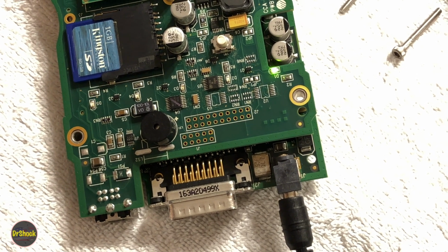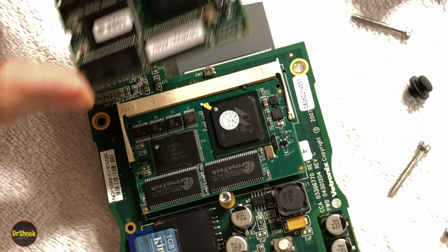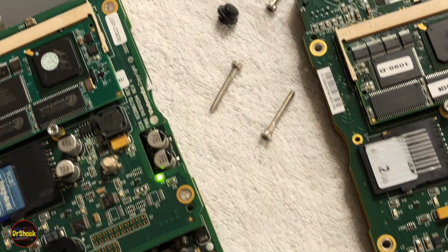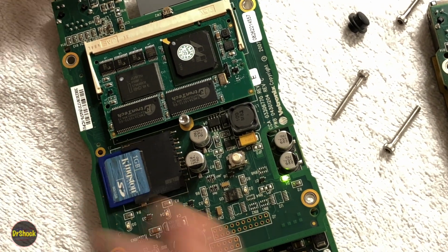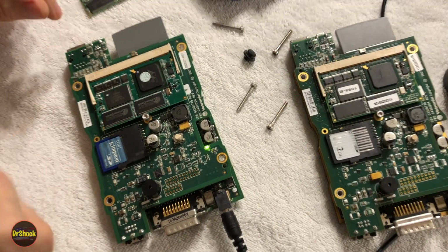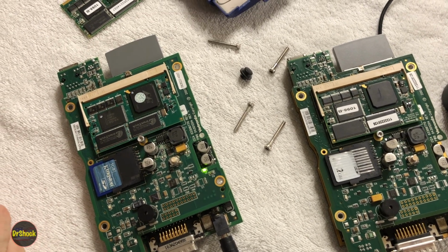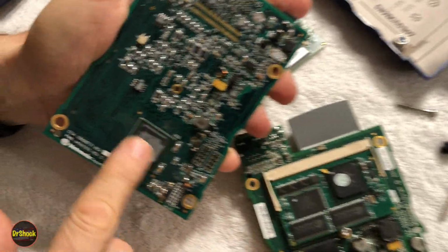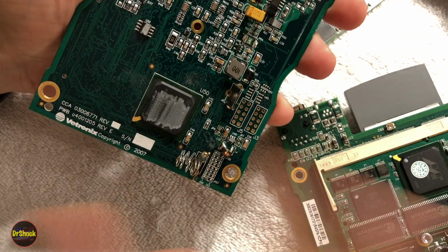Yep. That is that. Right, so we got two of them working. So the problem was this daughter board on this one, and the problem is the FPGA card on this one and on the first one. So that's at least a little bit more optimistic. You know, technically between the three, we can get two of them working now, hopefully. And you'd be able to then move forward with that. So again, we're going to go ahead and give a shot on taking the clone board, like I mentioned before. And in this case, we might start with the clone board and see about reheating this Altera chip and see if it does anything to change the outlook on it before we tackle one of the real ones.